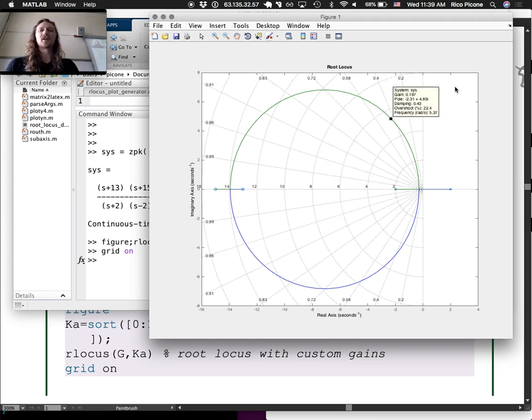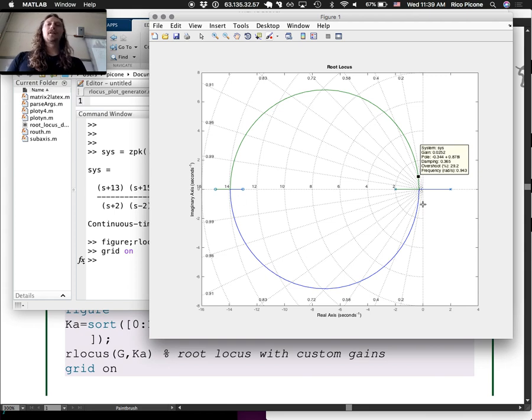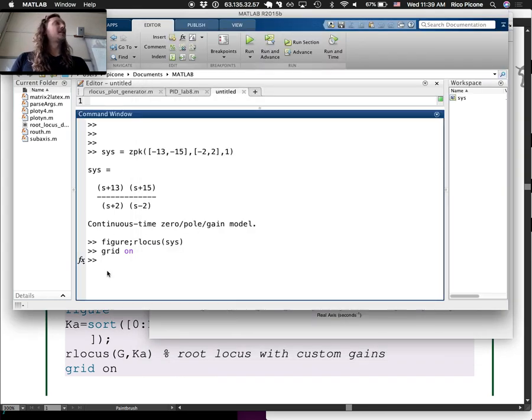If I go down here on the curve, this one's kind of unique in that you can get back down to the 20% overshoot. But once again, we don't have the resolution to do it. So there are two locations that we can pick. Okay. Now, what do we do because we don't have enough resolution here? Yeah, custom gain values. Our gain values that we used were just whatever the default was.